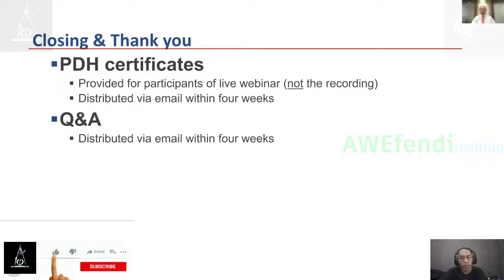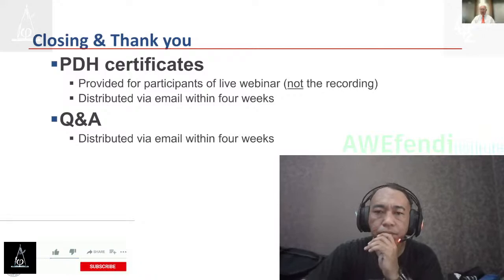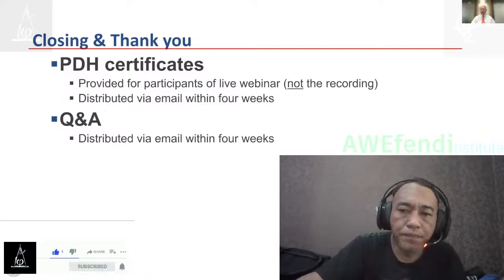That was the idea. For high-rise construction, so very tall construction, there is much to be gained from considering the dynamic response of the system. And so there still are triggers for modal analysis for high-rise construction, for tall structures, because that dynamic character is quite different from the simple characteristics identified in ELF. So I'm not trying to suggest that all systems should be designed ELF, but you should know that if you design a short building using the modal response spectrum analysis method, there may be behaviors that you don't pick up because it's a linear analysis, and ELF would have covered a lot of those problems.